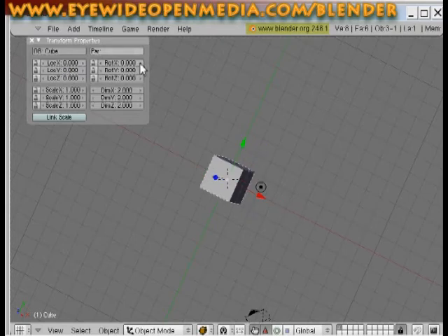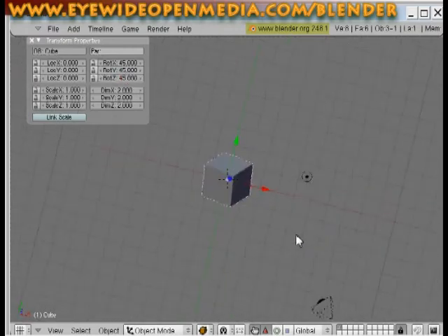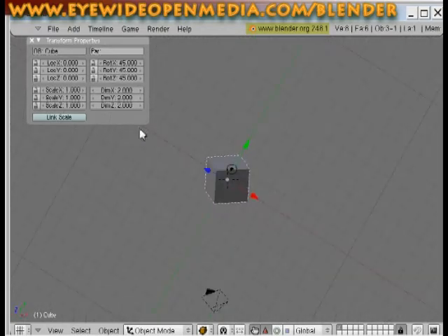Our rotation gives us control on each axis. If you see it on the x-axis, I do use this a lot. I don't use these arrows though. Sometimes I do in this aspect because I can go in increments of 10 by using the arrow. But normally I either want a 90-degree change, which you're not going to notice on the cube, or a 45-degree angle, which you'll notice. And if we want to just 45 everything, 45 the rotation Y, tab, 45 the rotation Z, tab, hit enter. Now we've basically put this thing on a 45-degree angle.